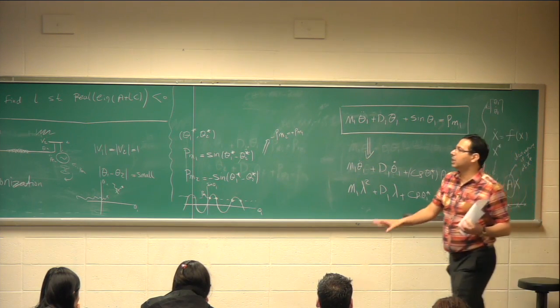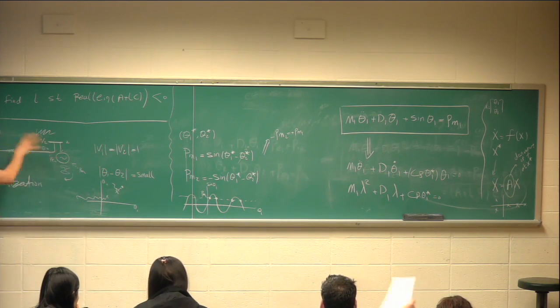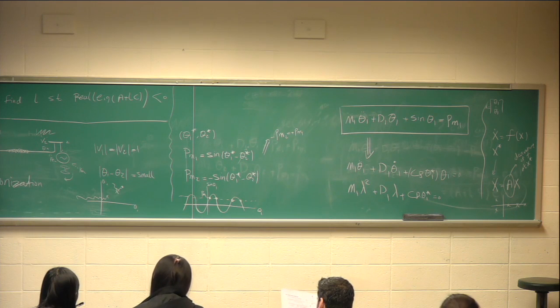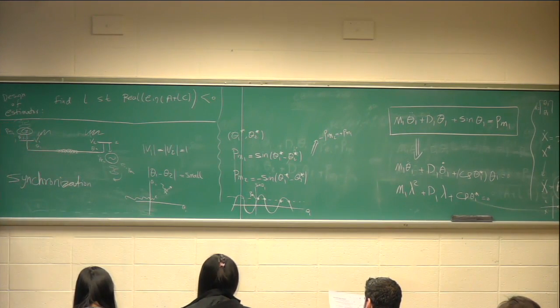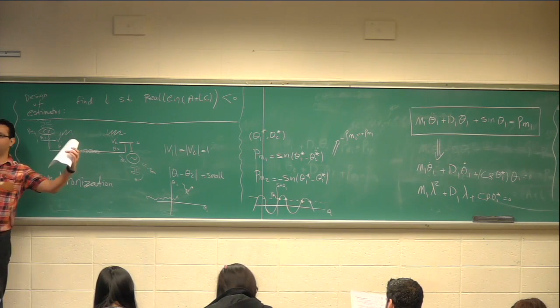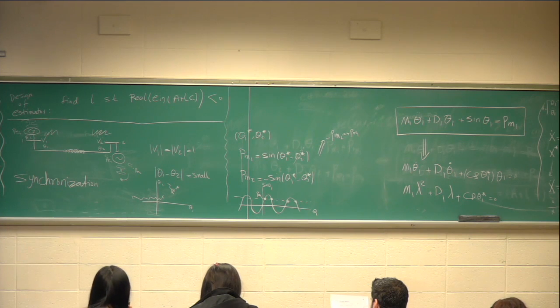But the main idea was the following: in a system with a lot of generators, depending on the mechanical power that we put in and the lines that we use, we get electrical voltages. These voltages should have angles that are very close to each other. Two sinusoidal signals. If the angles are very different, we are in trouble. This system is not going to work. So that's the main idea.